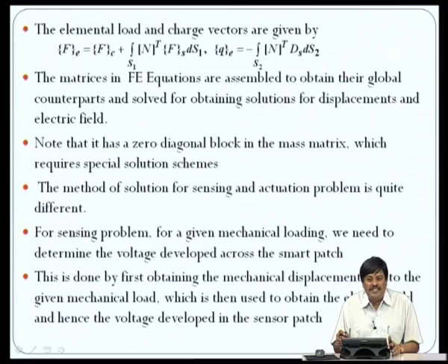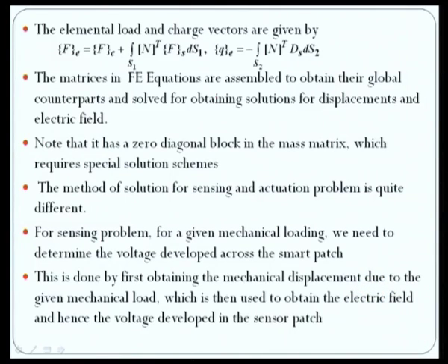The methods of solution for sensing and actuation problems are quite different. Now, we will see how we can do a sensing problem or an actuation problem. For a sensing problem, for a given mechanical loading, we need to determine what is the voltage, and this voltage will exhibit certain features which we can extract to do the sensing using a smart patch. So, this is basically done by obtaining the mechanical displacement due to the given mechanical load, which is then used to obtain the electrical field and hence the voltage developed across the sensor patch. As I said, this will introduce certain features and these features can be extracted to actually do a sensing problem.